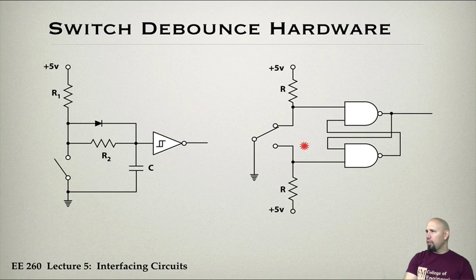And to handle this kind of switch, we use this kind of circuit. Notice both of these actually have two pull-up resistors. So even though this one is down here, it is actually a pull-up resistor. And then you have this NAND logic. It's a little tricky to follow. Each of these have their advantages and disadvantages. Some of these work well, some not so well.